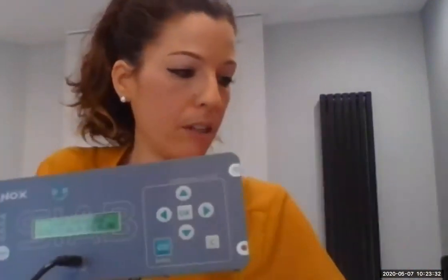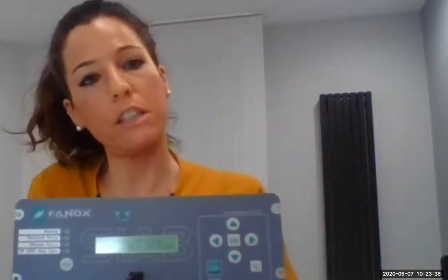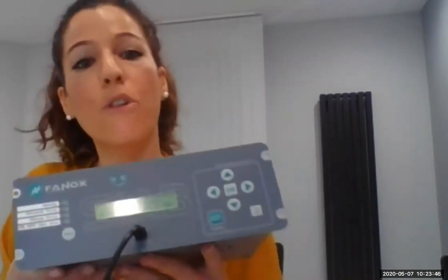Okay, you can see that it's bigger, but the reason, as I told you, is because this relay needs to manage any extra energy that can come from the CTs, because we don't know exactly what our clients are going to install. And this is the relay that is used for smarter end use with remote communication, and also for renewable energies, for wind power.